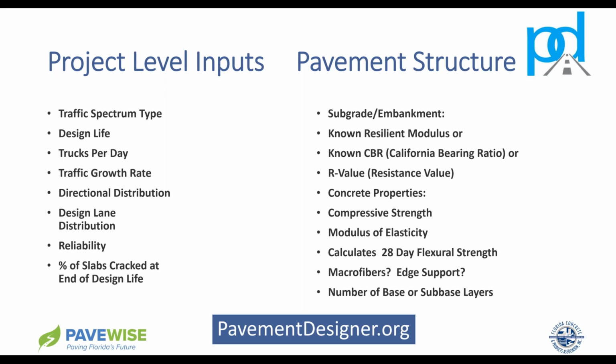Percent slabs cracked at the end of the design life. I like to use 10%. Some people like 15%. Some like 5%. And that again depends on the design. It may depend on your client, or the DOT may say, no, I want 5% at the end of life, I want 10%, I want 15%. You've got to figure that one out.